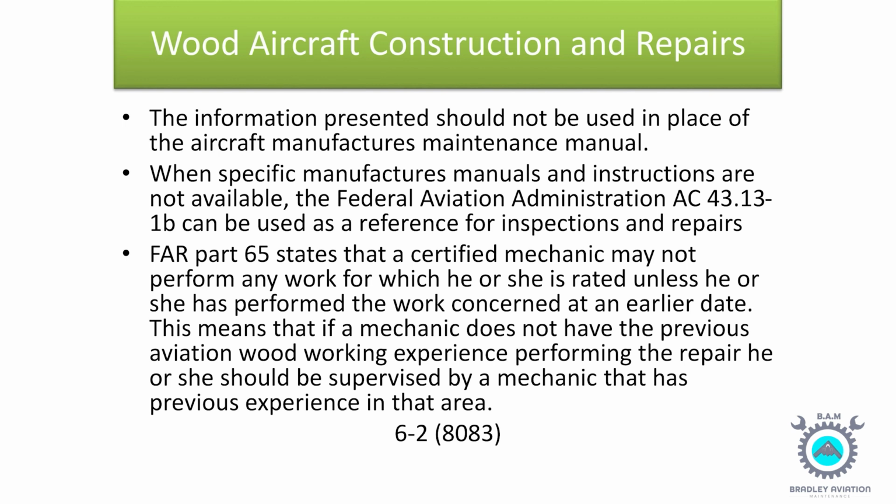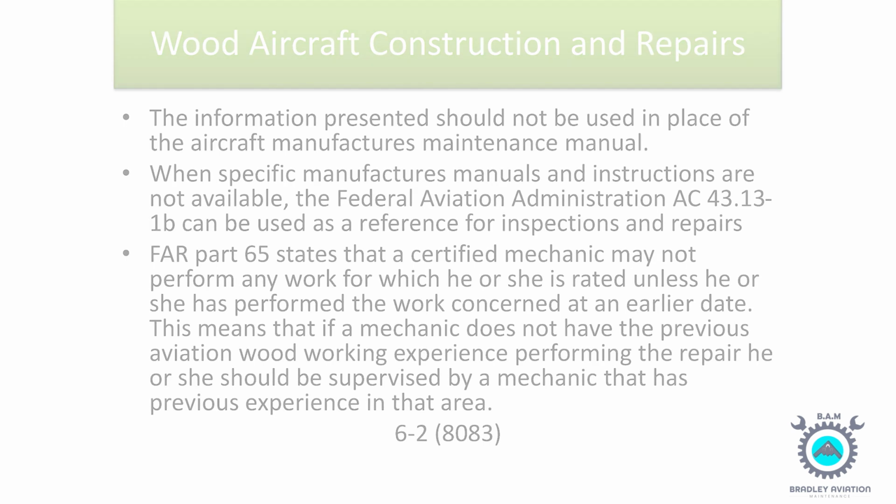FAR Part 65 states that a certified mechanic may not perform any work for which he or she is rated unless he or she has performed the work concerned at an earlier date. This means that if a mechanic does not have the previous aviation woodworking experience performing the repair, he or she should be supervised by a mechanic that has previous experience in that area.